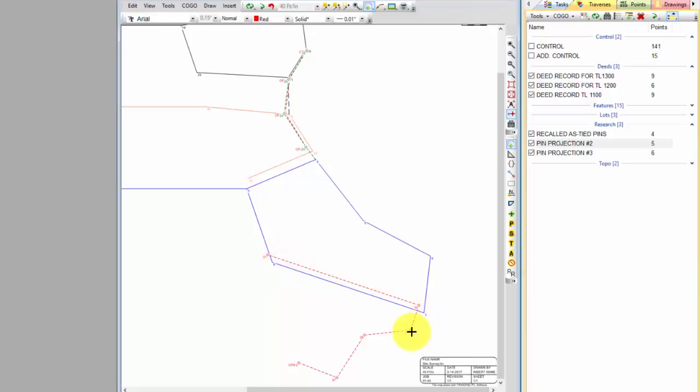I'm not sure I'm going to find anything. Maybe there were no monuments of record, or the record wasn't very good. I had a hard time kind of figuring out what might be there. But I'm going to create a projected position for those and search for those. And of course, if I find any, then I'm going to treat that as a found monument, come back to the drawing board, and I may change my decision about where to hang my hat on this. But I want to spend some time taking a look at what I found for monuments, projecting places to look for other monuments, and then sort of doing the due diligence necessary for me to do a good job on this survey.